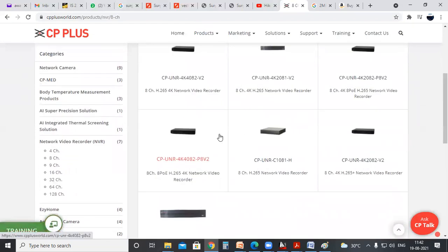So when you do the design for CCTV, the most important thing you have to make sure is that the NVR should be in a highly protected area, because normally when thieves are entering buildings, they know nowadays every building has cameras. So what they do is they'll be taking the NVR along with them. Okay, so make sure that the NVR is not provided in a common area. You can provide it in a master bedroom or some area like showrooms with safety, so that even if a person is trespassing in your area, he will not be able to find the NVR location. Then it will be good.